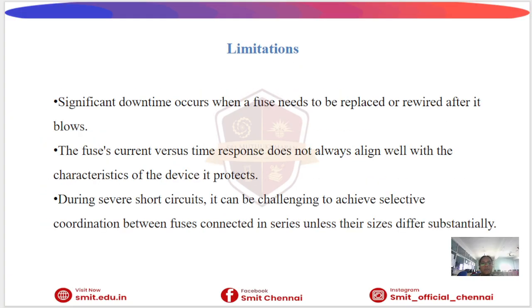Limitations. Despite their advantages, fuses also have some limitations. They must be replaced after operation. Next, sometimes the time-current characteristics may not match the equipment. Then, selective coordination between multiple fuses can be difficult.